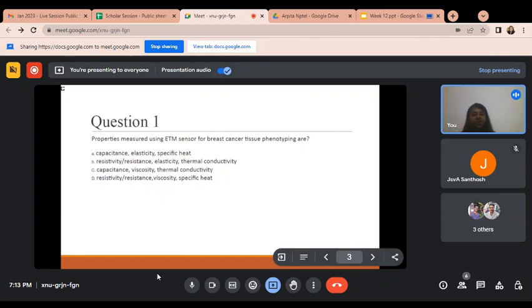So RCA1 cleaning process is a standard cleaning process. Why is it required? To remove the organic contamination from the wafer surface, we use the RCA1. And how to prepare this RCA1 solution? There is a 5:1:1 ratio: DI water, H2O2 and NH4OH.